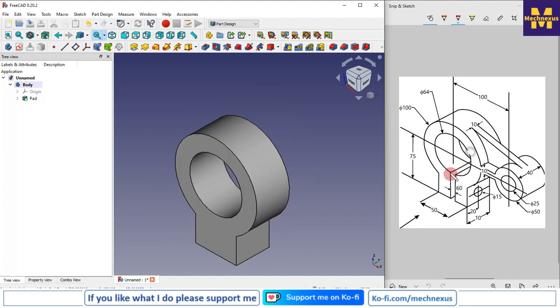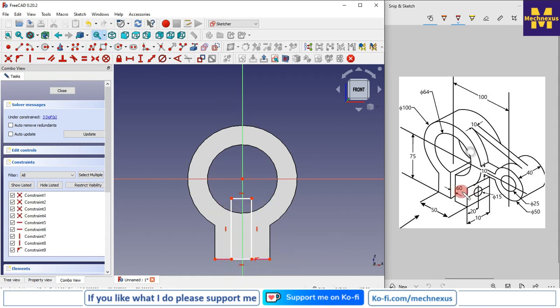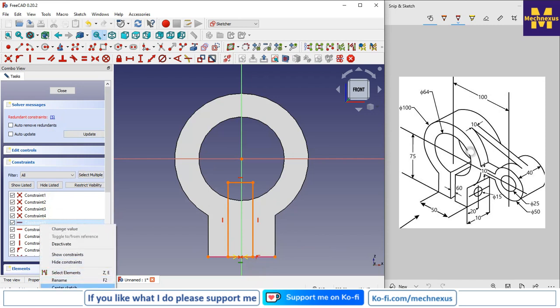And now we will make this cut profile. So I will select the face and create a sketch, and I will project this bottom edge, and I will draw a rectangle. Here it is 60, so here also the dimension is wrong, it would be 6 mm. So I will select the symmetric constraint and make it symmetric, and I will delete this constraint.